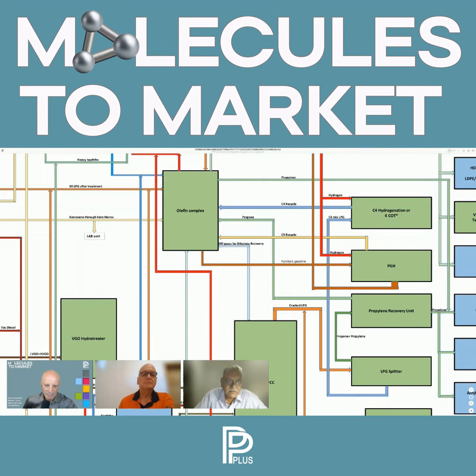What we have done is that when we do the basic engineering, within 3 months, that means at the time when the process flow diagram is complete, heat and material balances are done, the dimensioned equipment layout must be frozen. The consultant should make it, licensor should also agree and stamp it, so that all further hydraulics work on the plant by the licensor is carried out on the agreed plot plan.